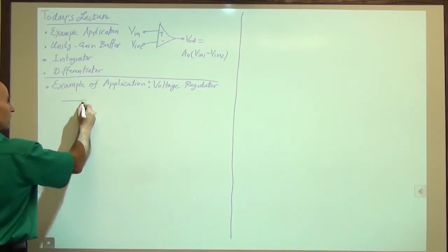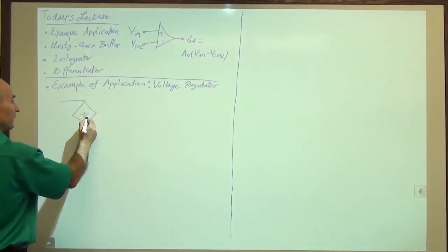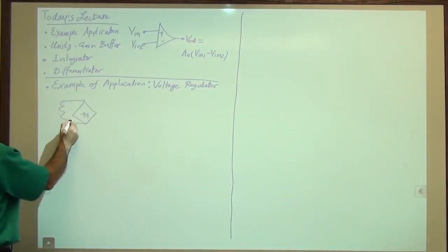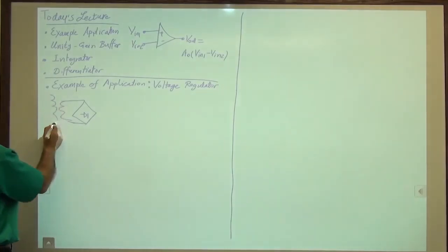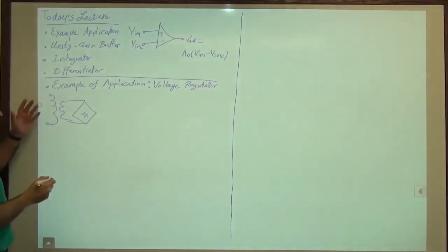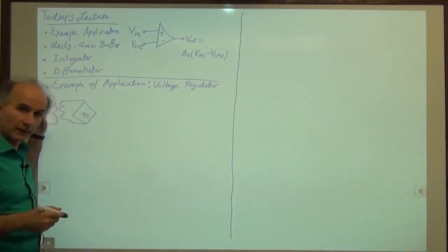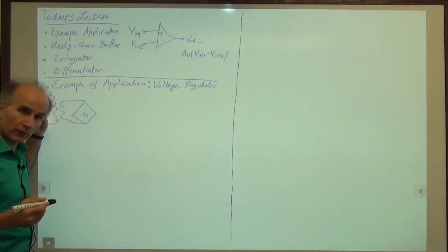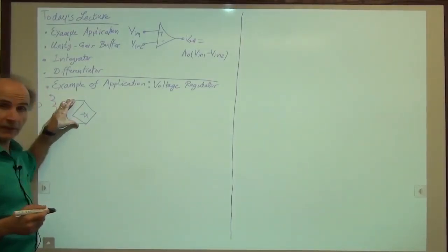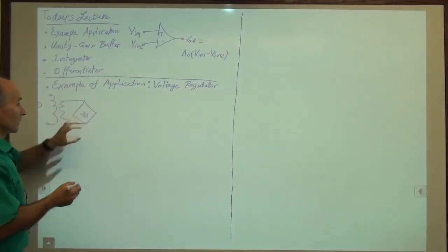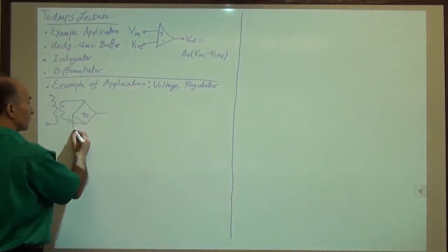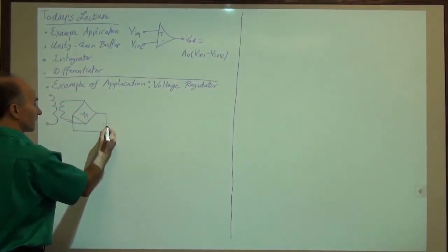We had for example, a diode bridge. Before that we had a transformer. So at the primary of the transformer, we connected 110 volts or 220 volts. That gave us something here, maybe 20 volts. We rectified it, full wave rectified it, and gave it to a capacitor.